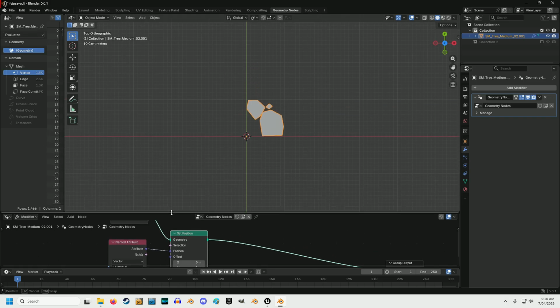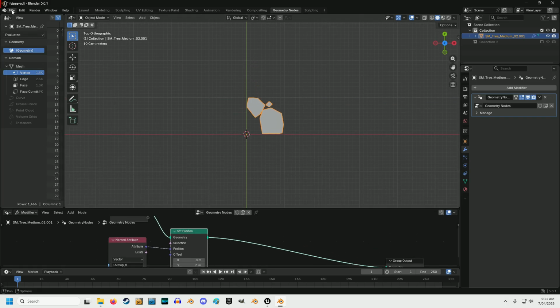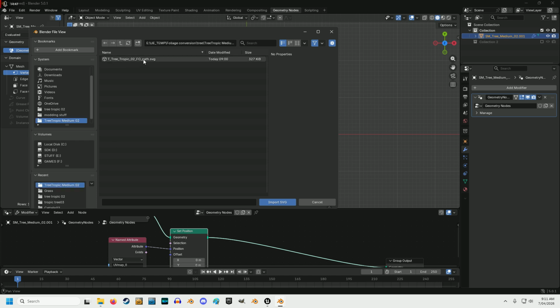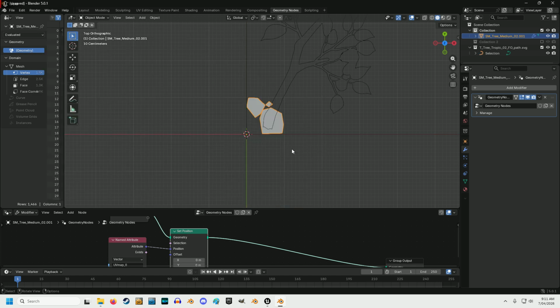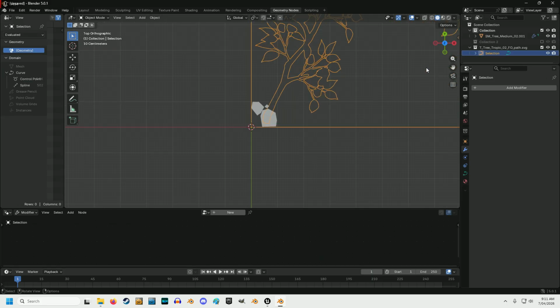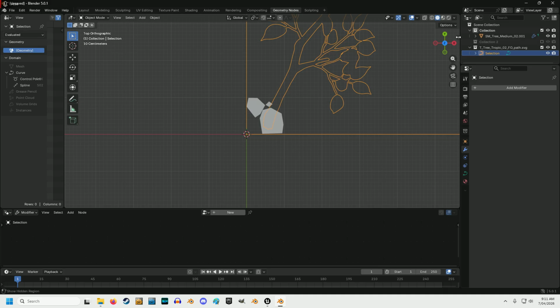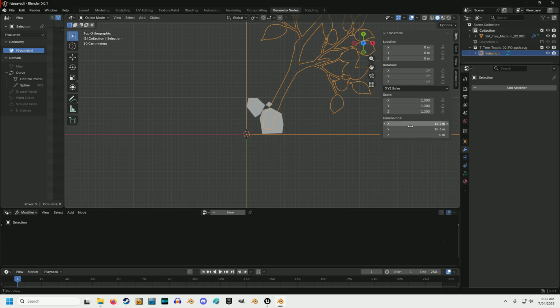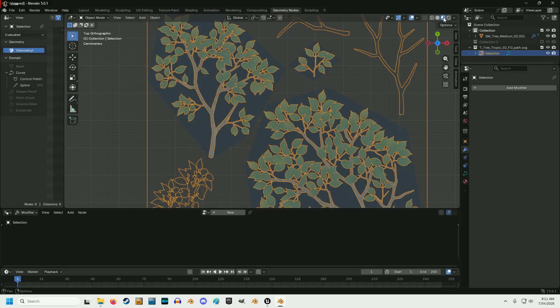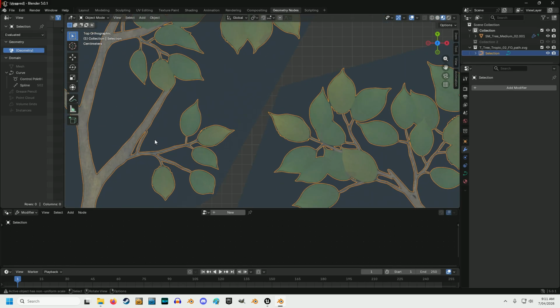The next thing to do is to bring in our tool, which is the path. So we'll go up here and import SVG, go into our folder and import the SVG file. You can see here that it's quite large, so what we need to do is reduce that. If you go up here to this little arrow, pop that out, go down to these ones, left click and drag down the first two, and then set them to 1 by 1, so that'll make it 1 by 1 meter. And now everything lines up with our geometry and our texture.